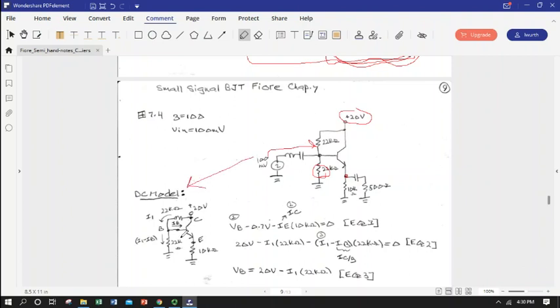So this is what DC sees. Good old voltage divider bias that we've done before. We can assume this is lightly loaded, and so we can basically just say the voltage at point B is going to be 20 volts divided by 22K plus 22K, and then multiplied by 22K, so we'll have about 10 volts at point B.